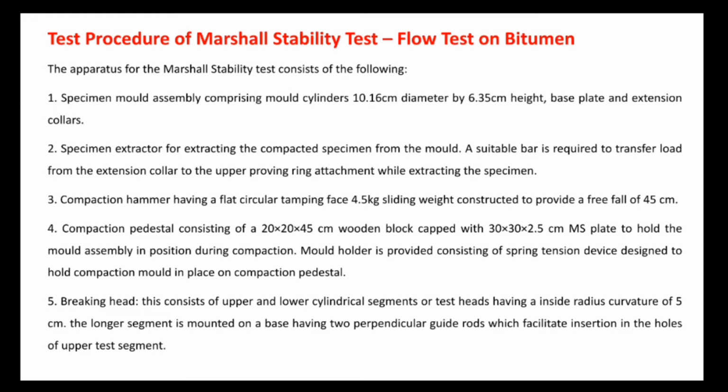It should be understood clearly that whenever the sample is placed for its testing, whatever is the maximum load it can bear, or the load where it actually fails, that will be taken as the stability value, whereas the corresponding deformation will be taken as the flow value.